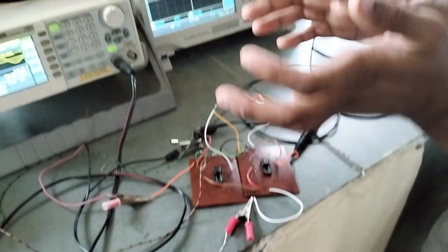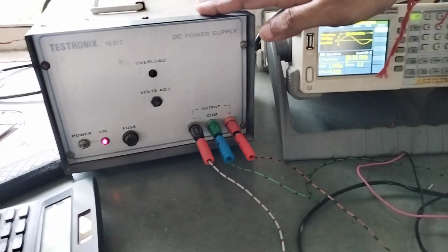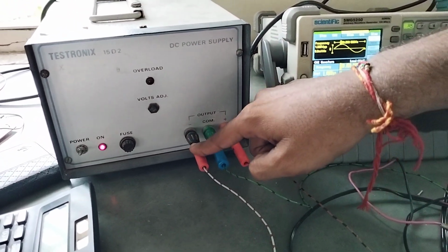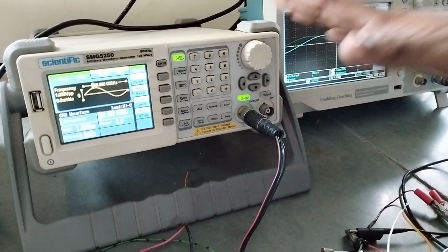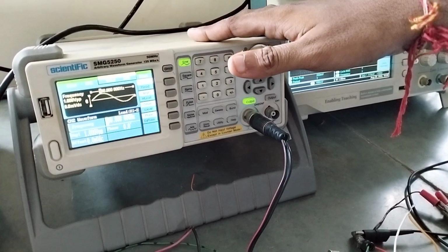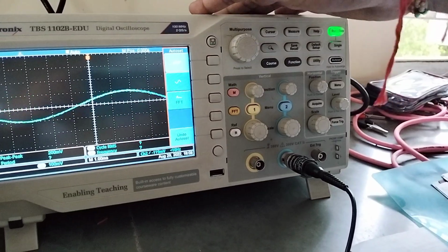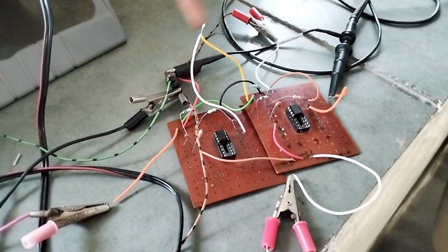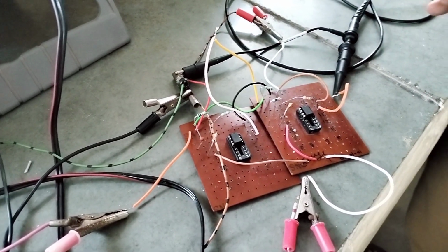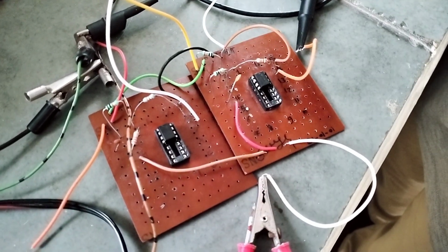Now let's see what happens after connecting both circuits. Let's see the output. This is my circuit. This is my 15 volt power supply, with positive, common and negative all connected. This is my input, known as the frequency generator, and this is my oscilloscope, with which I see the output. This is the wire I connect to output and ground. One of the most important things in this practical is to use the proper instrument wire, so you get your output very precisely.